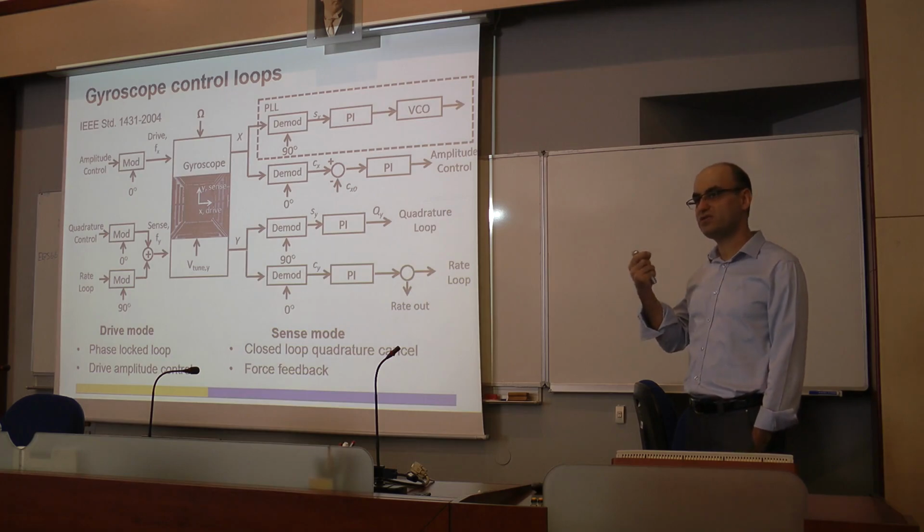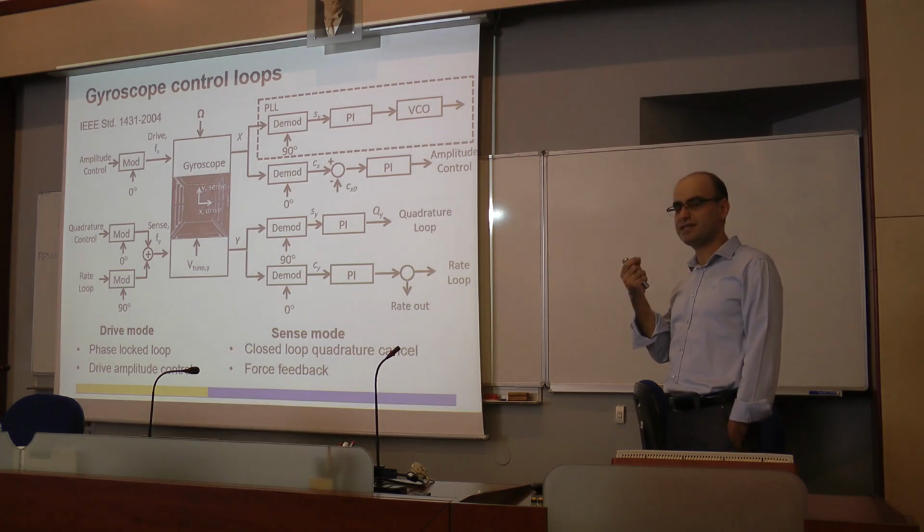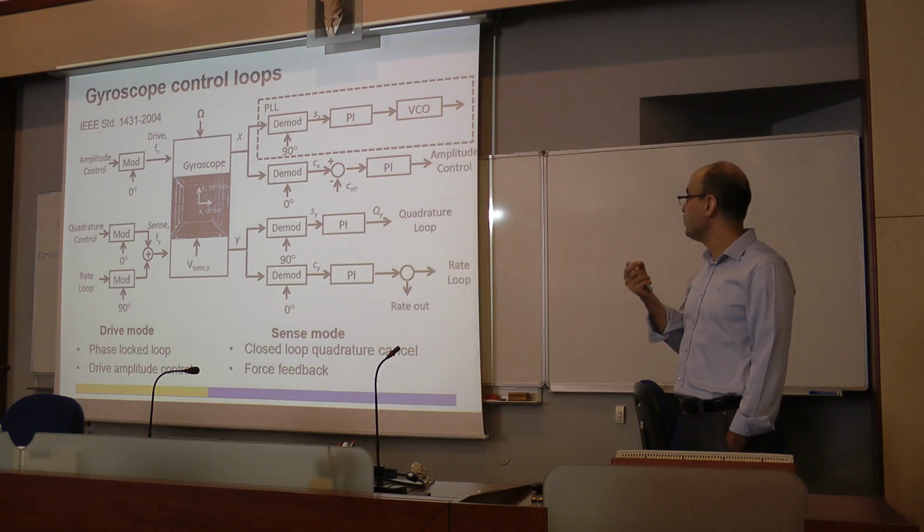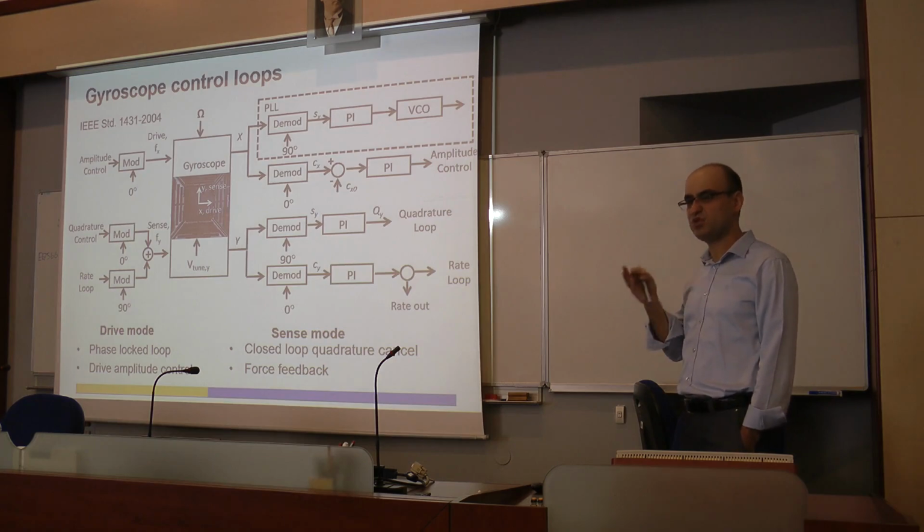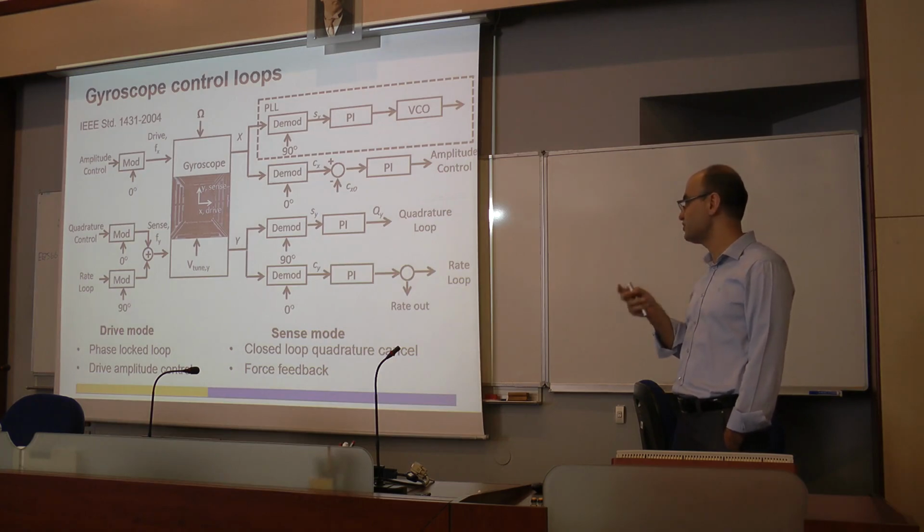Once you lock into the frequency, locking is not enough. Then you also need to fix the amplitude of the oscillation so that your Coriolis force becomes stable.